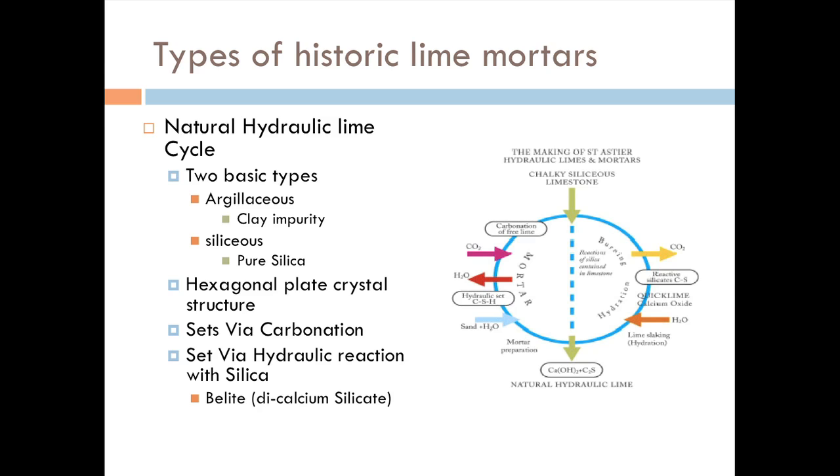In fact, I can look right now behind me, or behind all of you, I could see that very long stretches of brick were laid, maybe 40, 50, 60 feet in some areas. Today, we have to accommodate that movement with things called control joints, like the control joints that you see in a sidewalk every 4 feet, because cements can't accommodate these movements. But lime can, it can flex. And that crystal structure allows that to occur.